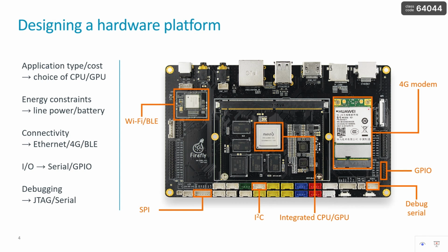How the system will interact with peripherals influences the choice of the IOs. Here we have the GPIO, general purpose input output, and different types of serial interfaces, such as the I2C, which is the inter-integrated circuit, and the serial peripheral interface, the SPI. Consider it as the way that I'm connecting my hard drive. I'm going to use SATA, or USB, and different types of USB: USB-C, USB-A, and so on.